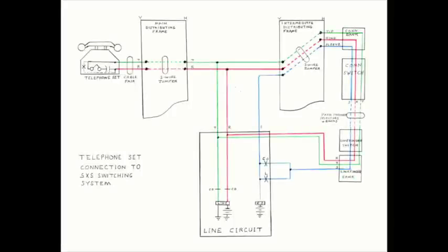At this point in time, the ring wiper, the tip wiper, and the sleeve wiper are all resting on terminal 00 of the bank assembly. So at this point in the progression of the call, the connector's tip, ring and sleeve wipers are physically connected to the called station's line circuit, and the tip and ring wipers are physically connected to the called station's telephone set.